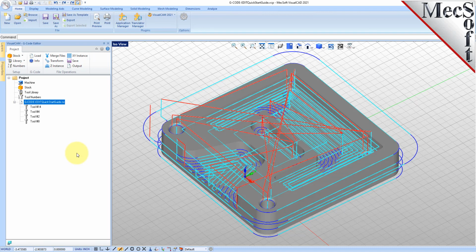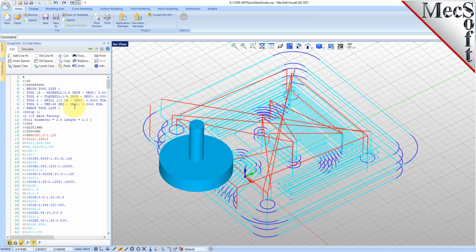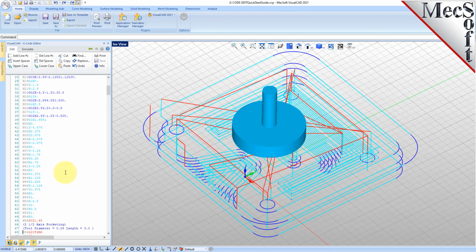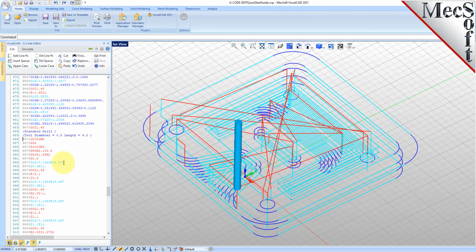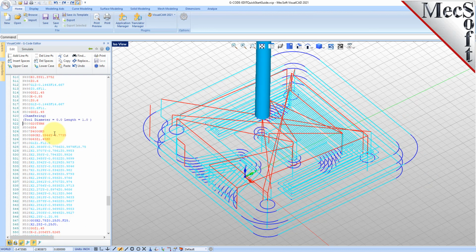Okay, let's perform one additional edit to the G-code file. This is a common edit that users perform, so I'm going to show you how easy it is to do by editing the G-code file directly. We're going to right-click on the G-code file on the Project tab, pick Edit, and right-click anywhere in the G-code file to display a pop-up menu of commands. Now these commands, bottom, top, tool, spindle, feed rate, are navigation commands. For instance, you can just go to the next tool and it'll go to that line with the next tool on it. Pick tool again, it'll go to the next line for your next tool, and you can work your way through each of your tools, and it'll show you in the line of G-code where your tool is defined.